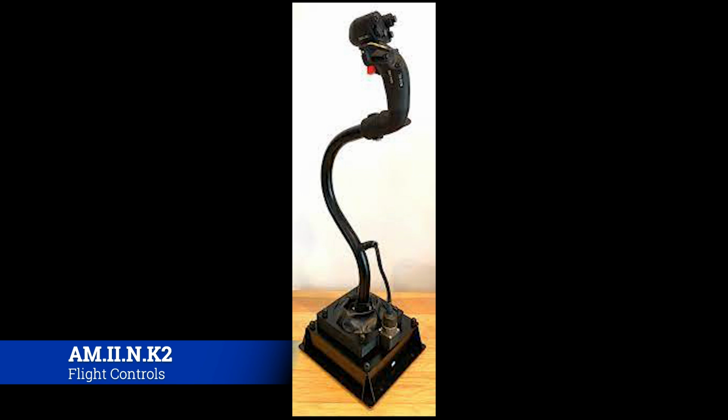Now keep in mind, as you move the cyclic around on the ground, you'll see those pitch change links move up and down. If you were to go forward, you're actually going to see the right side of the pitch change links push up because of gyroscopic precession. As you input the controls, you only get the effect of the spinning disc 90 degrees in the direction of rotation. So you'll see the rotor disc come up. Same thing if you were to pull back, you'll see it on the left-hand side come up. And so it can be kind of confusing until you understand what's going on with gyroscopic precession and the cyclic.